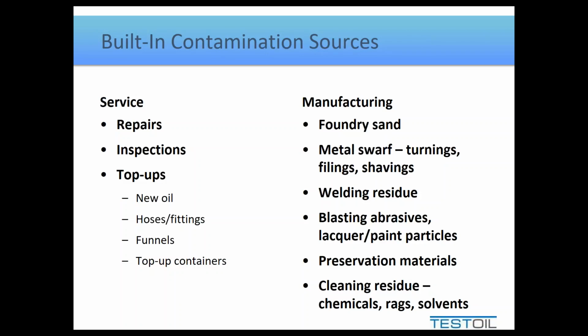Further down the service column, anytime we do an inspection, something as simple as pulling a dipstick out to confirm a level, opening a hatch to look for foaming, things like this will allow the opportunity for contaminants to get in. And then definitely top-ups. New oil is not clean oil. You're going to learn more about that throughout this particular webinar.